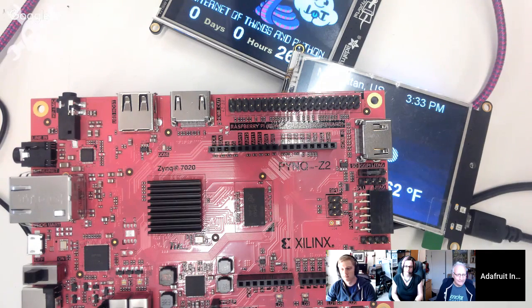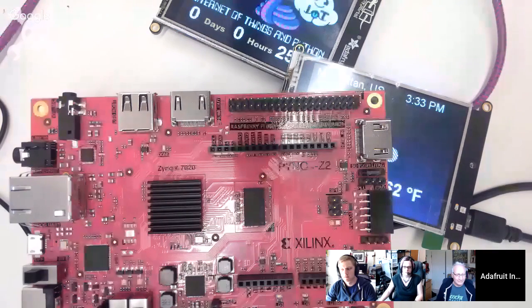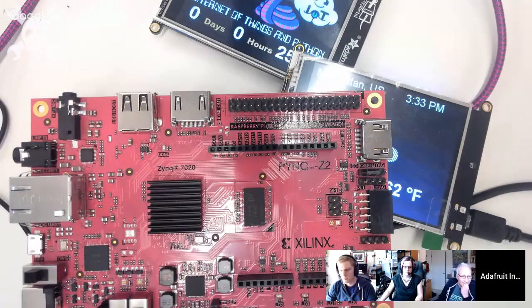Okay, wondering if there's any way to run a CircuitPython board at less than 0 degrees Celsius. I don't think... well, you can always just try. You can run a Circuit Playground Express at below freezing. It'll probably be fine. We tend to use commercial temp parts because they're less expensive and it covers most uses. It'll probably work okay down to -20. Not great, but it'll work.